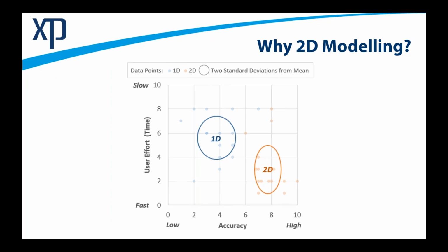So in many catchments, and this is more suited to overland flow, 2D modelling is more accurate and it's much quicker. There are still some very valid uses for 1D, so I'm not saying that 2D is the only answer. There is always a need for engineering judgment when you're designing your models. But in a broad sense, it is typically more accurate and easier to develop a model.